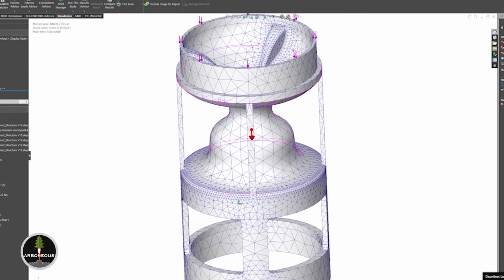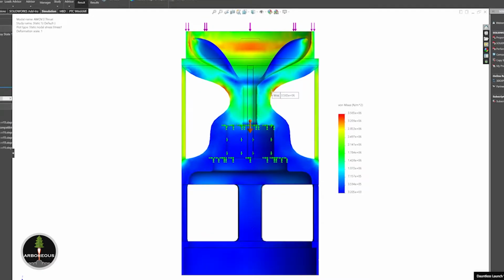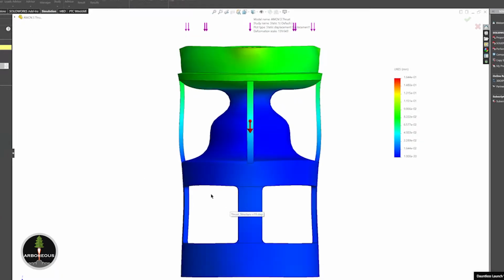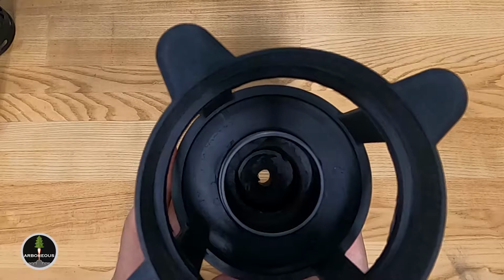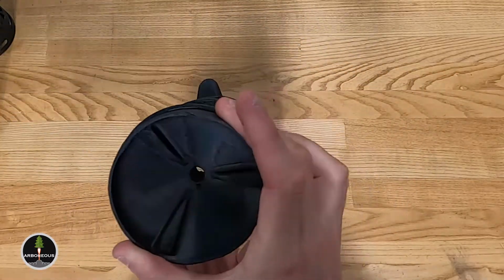The new design of the thrust structure allowed the loads to efficiently transfer into the upper sections of the vehicle while drastically reducing the mass. The new contours of the motor mount allowed us to efficiently transfer the load while drastically reducing the mass. Results from testing showed that it could withstand up to 25.8 kilonewtons, or even 5,300 pound force.